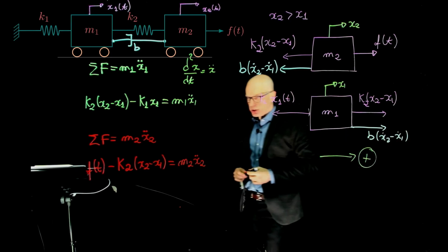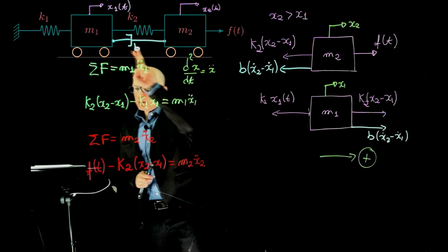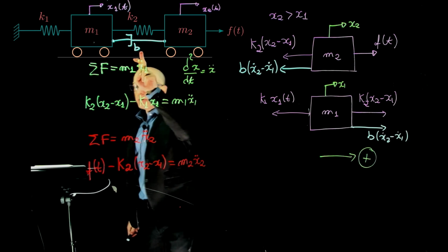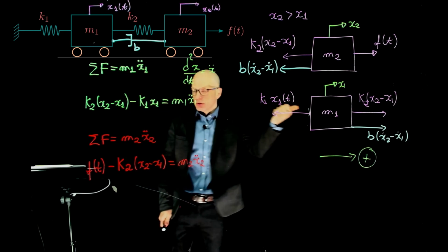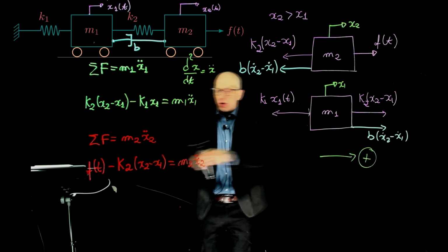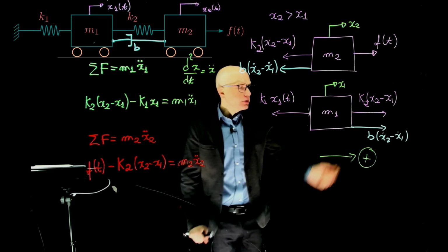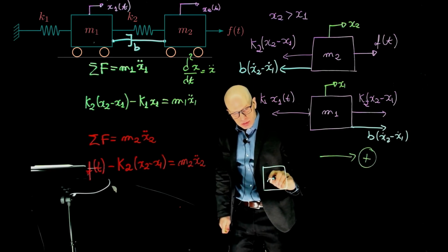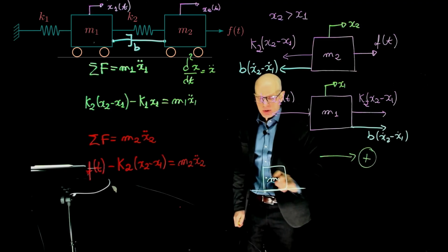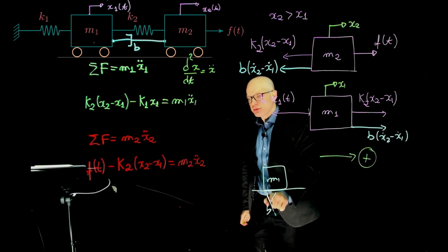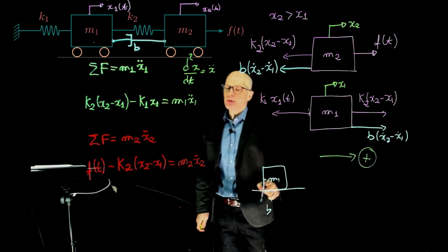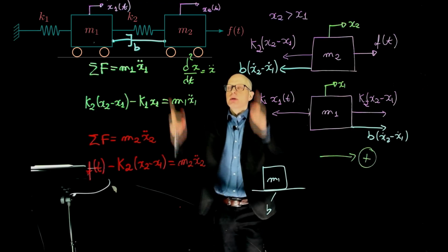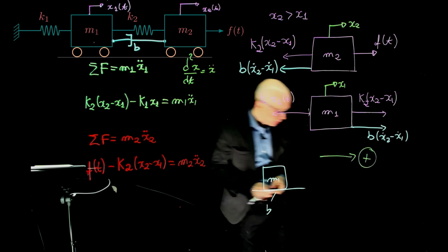Now in this case, look, the damper is actually accelerating mass m1, because mass m2 is moving to the right. The damper is creating a force and is dragging m1. So this is actually accelerating the mass. Whereas if we had something like this, for example, with friction between these two surfaces, it would always be slowing down the mass. Right? But it's the same type of friction. Here, though, it's an element that exists between these two masses.